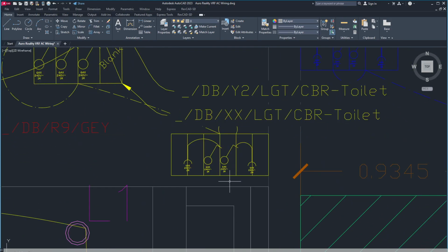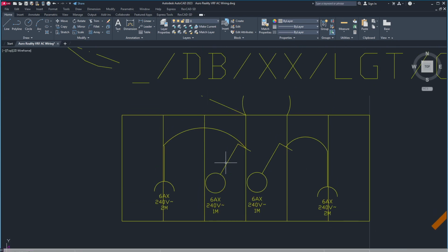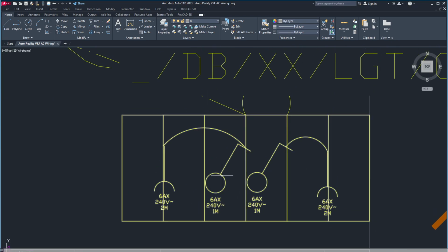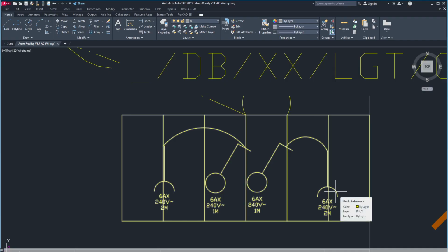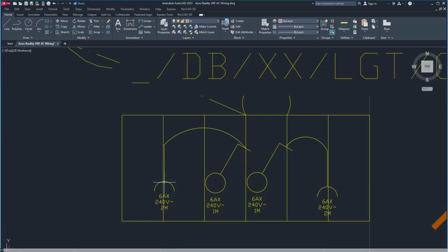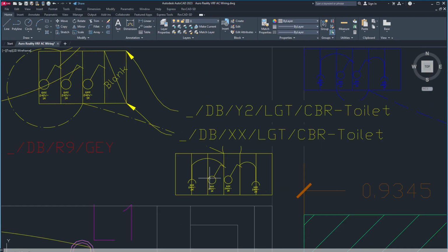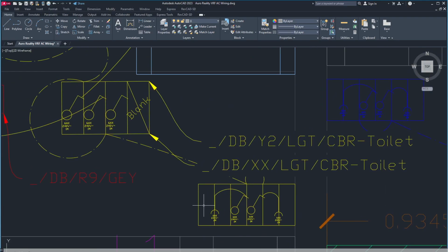And a better engineering practice is not to hard code the light for this, because most of the designers will give a light. That means this switch is 100% fixed to that light only. Down the line, if the client wants to put a phone charger in this socket, or here wants to have his CPAP machine for sleep or body massager or some other machine, then there is no scope. So this is a superior design. If he wants a light, he can always plug in a light in this. So this is much more versatile.